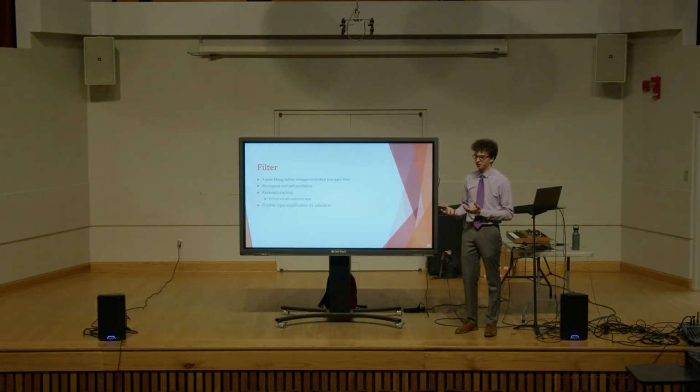This filter includes resonance and self-oscillation once you push the resonance past a certain amount, which is very desirable to me. I also intend to implement keyboard tracking, so that you have a range on a knob, say, and then you can change the cutoff of the filter depending on the note that you press on the keyboard. At its maximum keyboard tracking value, it would change the cutoff 1 octave per 1 octave played on the keyboard, and that lets you